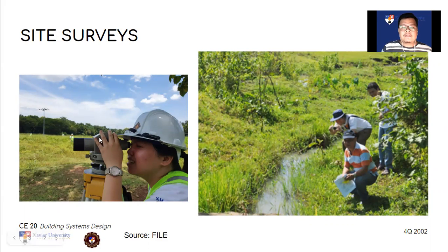If you don't have that luxury of equipment and time, then you can just do reconnaissance survey. Just pick up a camera or a cell phone and then plot these points in a map, and this will guide you on how you can better design your site, your proposed lot, or even if it's a subdivision plan.